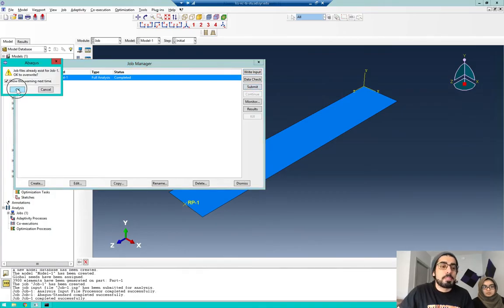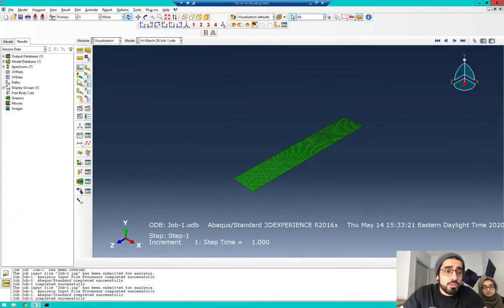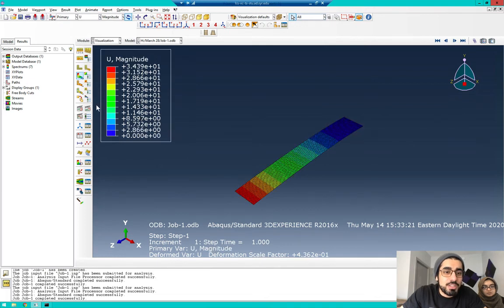Okay, and we click on results again, and we go to the contours, and we find this is not the results. Okay, again, this is von Mises stresses. Make sure what you're selecting here. Okay, and you go to units here, and how much is it now? 34. Now it's almost the same results that we got. Okay, 34.39. So again, we got the result 34.39.